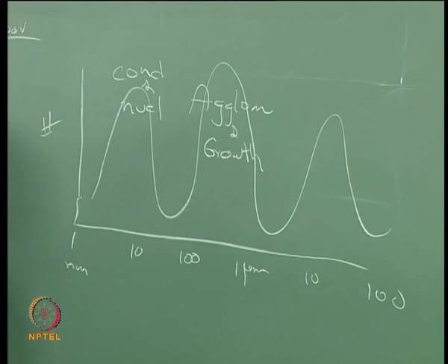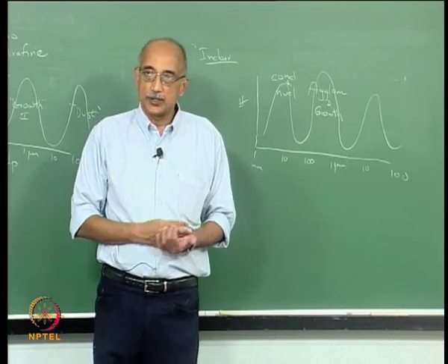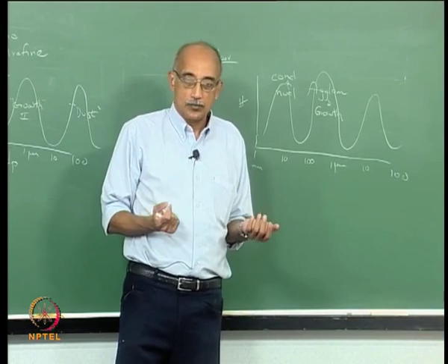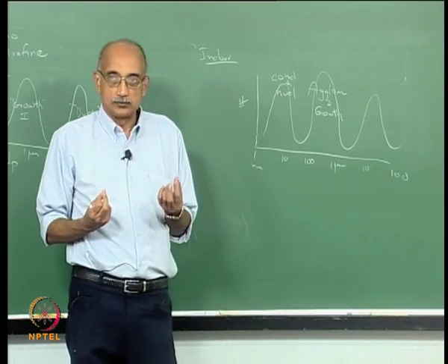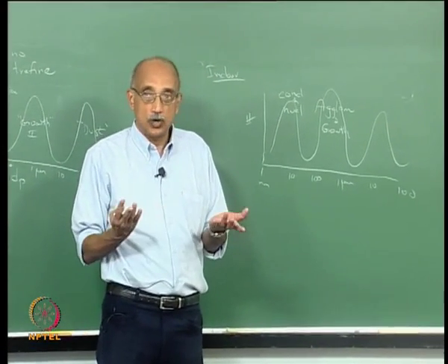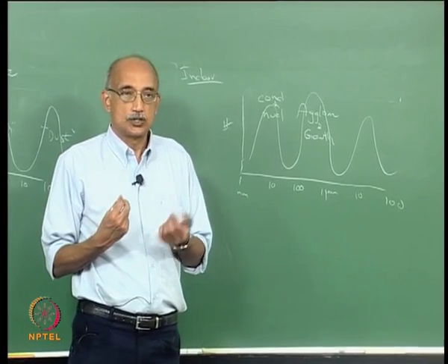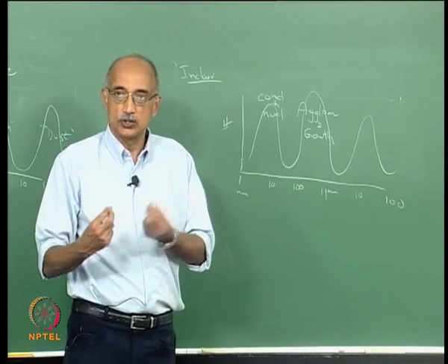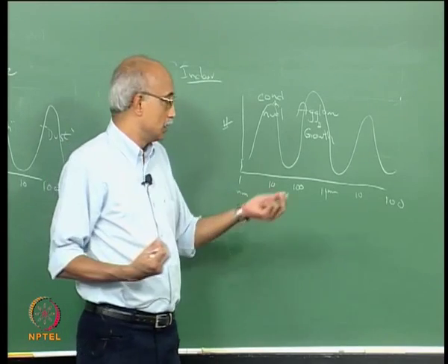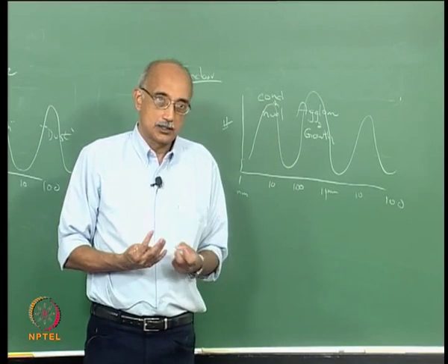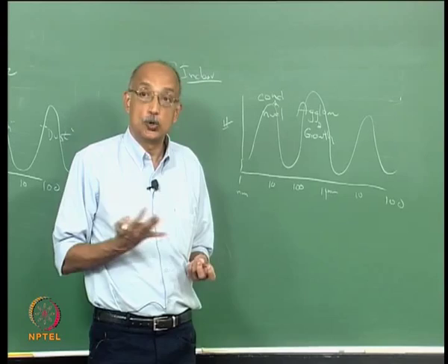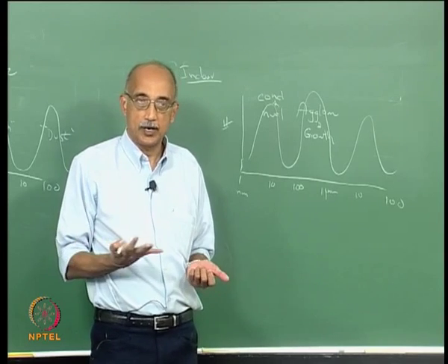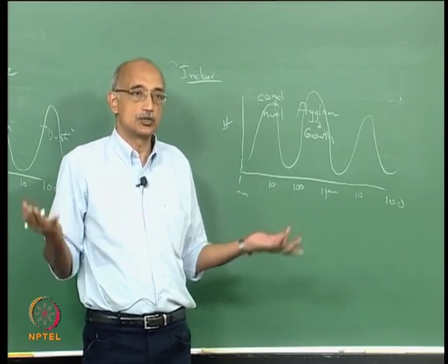Although the extent to which this happens again depends on how clean the room is. For example, in a well designed clean room, particles are present in a very dilute form. The number of particles per unit volume is very, very low. So the probability of one nucleated droplet finding another one is also very low. So agglomeration kinetics are going to be highly slowed down in a clean room type of environment versus an uncontrolled environment.